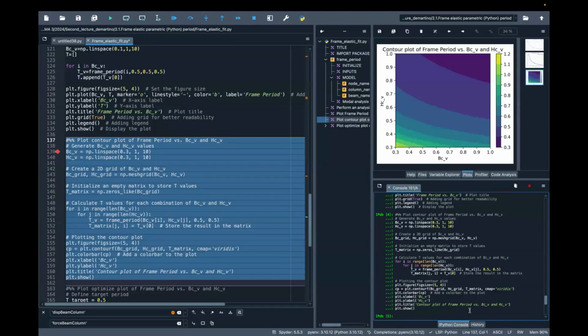Obviously, again, we can make a check of our model: increasing the height of the column, the period is decreasing, right? You can see we are moving from light to darker color. And similarly, increasing the base of the column, we are decreasing the period. And obviously, when we are moving both variables, we are moving.